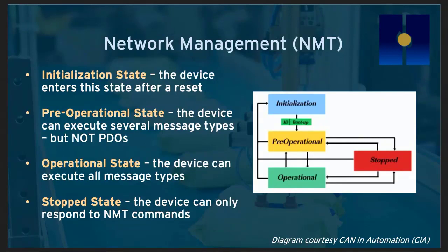In this state, it has some capability to talk on CANopen. Namely, it has the ability to respond to SDOs and some other types of messages, but it can't handle PDOs at this state. Just SDOs, just occasional messaging. No process data, no runtime data at this stage. Now, when it goes into the operational state, and the master is typically the one who puts it there, it can execute all CANopen message types, including the runtime PDOs.